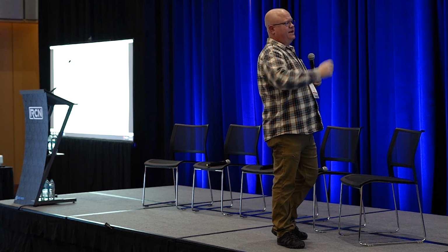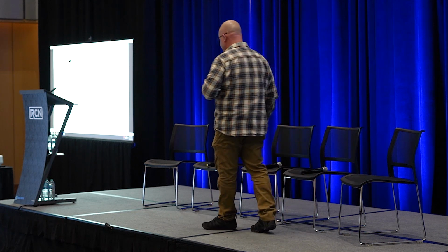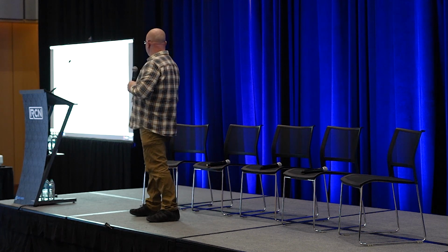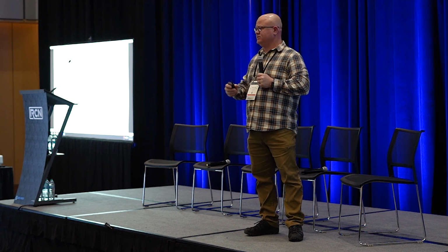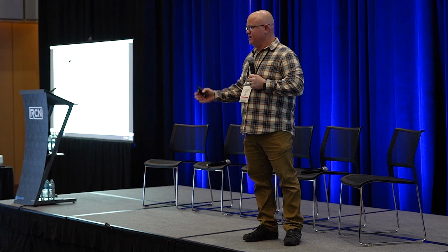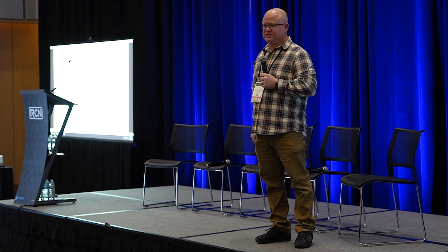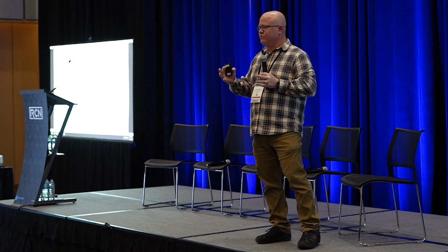So you can see here, not only in ACC, you can work with the point clouds for visualization. We can also use it for model coordination. In ACC Pro, that's the next level up from Docs, we're able to do what's called model coordination. In model coordination, we don't use the point cloud, we use the mesh file. We can actually push out a Navisworks file that's got the mesh, bring it into model coordination, and coordinate it with anything that's in the same coordinate system. If you've got buildings around, a site that you've designed in Civil 3D, or a DWG that's in a coordinate system, that can all be put together and you can clash against it. And that's in what we call ACC Pro.